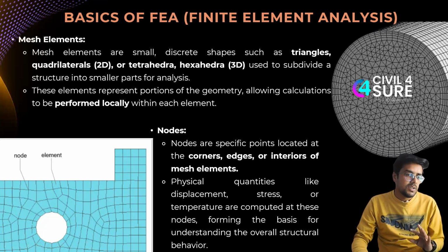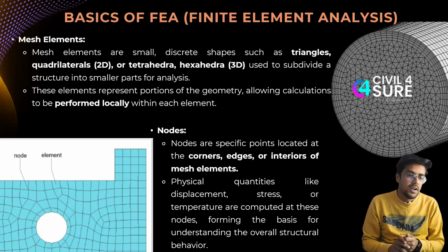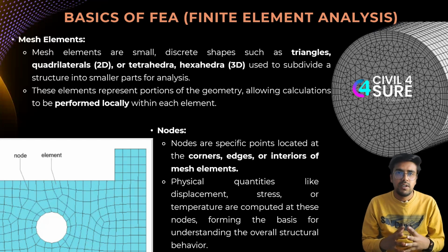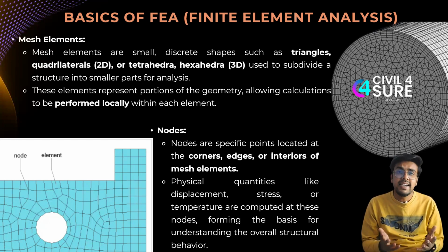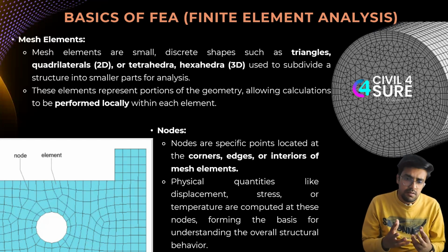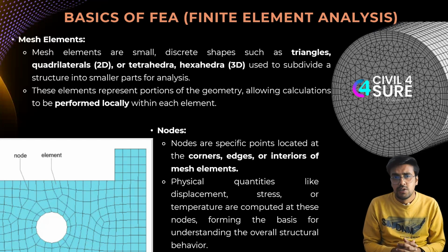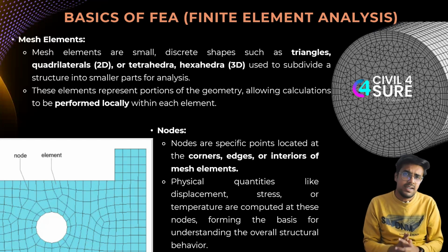See, the meshing can be a bit complex, or it can be a bit simpler. It gets simpler when we don't want it to be very precise, we just want a simple thing like ETABS does. ETABS includes a default mesh setting for the slabs. So even if you don't select the meshing option, it is going to mesh it by default, and it does it very well.